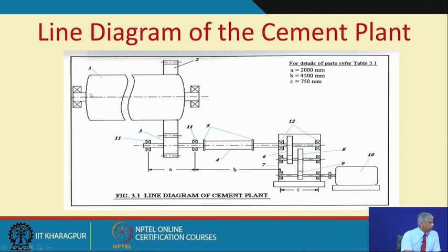Of course, it is sometimes inclined, and then the raw materials for the cement, like limestone, fly ash, etc., are added. Okay, and then there is a big grinding media, nothing but strong vanadium balls. So, this is rotating, and of course the drum has a liner which will protect it against abrasive wear and tear. Because of this grinder, at the other fine end you will see the fine powdered cement coming out, and there will be a sieve, etc. But the fact is this big drum has to be rotated at 2 to 3 RPM.